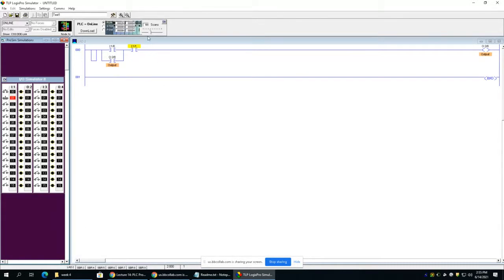One last thing before I sign off, this button right here. Now, PLCs do not have this scan button. This is something that's unique to the program, but you can actually speed up and slow down your program scan. So when you're troubleshooting, actually later on in the semester, you'll probably use this. You can slow it way down and kind of walk through your program to see where there's trouble. So I'll tell you more about this scan button.